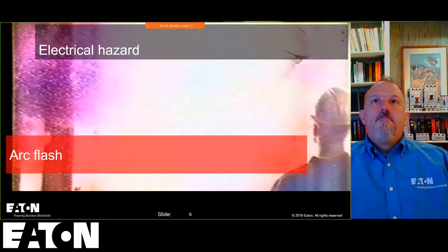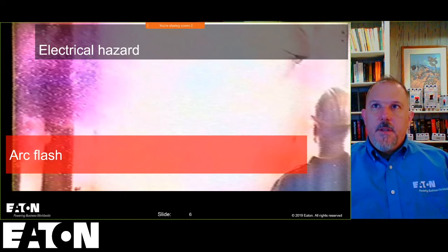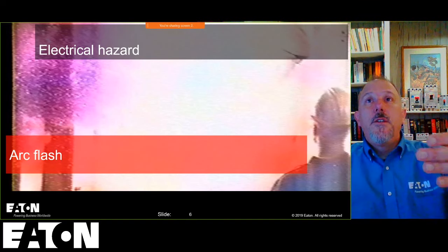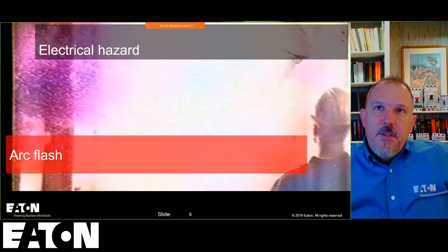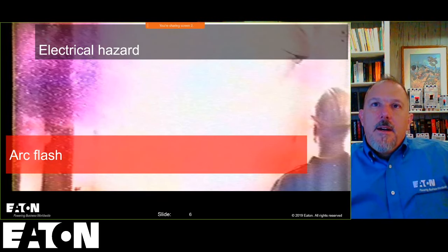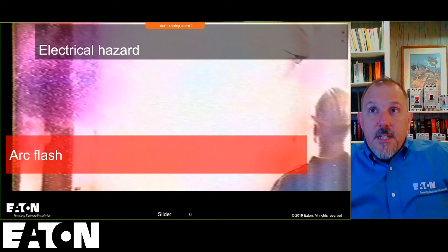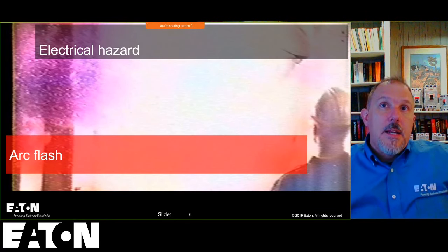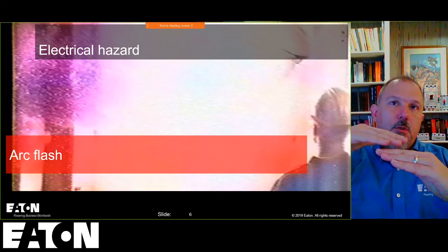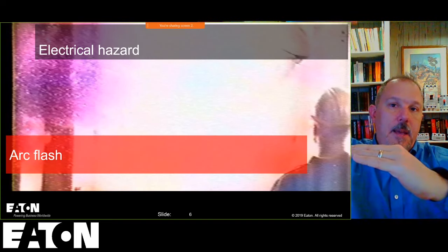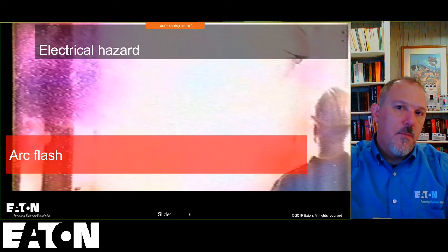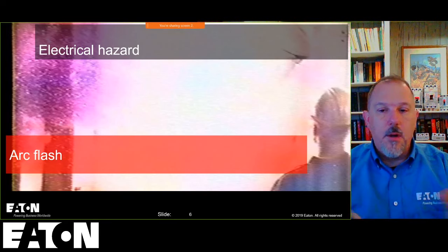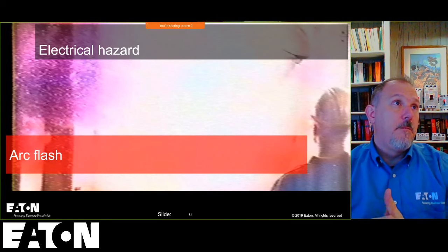Okay, I'm looking at the feedback here on YouTube. Usually my WebEx guys are more chatty than my tubers, but the YouTube people are giving good feedback. We got a great pro tip for improving clearing time. Absolutely. The Eaton double door fusible safety switch is a smart way to separate the line and load sides. They put the actual switching capability up top, and it's even got a barrier, and then down below is where you have your fuses. So when you open that switch, you can't open the top door, you can open the bottom door, nothing in there is energized, which gives you good separation.